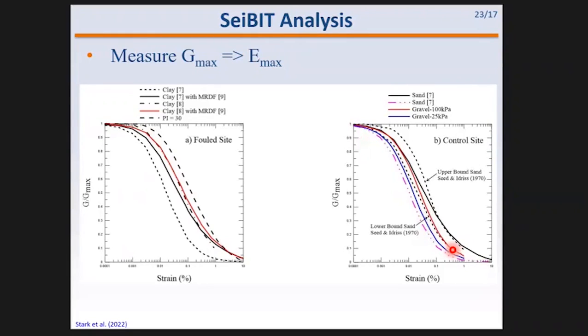The second question is, does the amount of energy applied to the test affect the shear wave velocity? No, and the excitation source that Chuck developed has about 8 different settings of energy into it. So it cycles through all levels of energy.